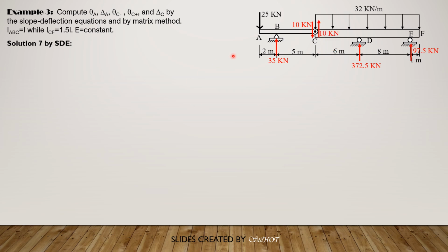So we need to have moment BC and moment BA. Moment BC is negative 25 times 2, while moment BA is positive 50. Negative 25 times 2 is negative 50. So if moment BC is negative, then moment BA is positive from slope deflection equation, because clockwise moment is positive. So that's why moment BA is clockwise, so it is positive.